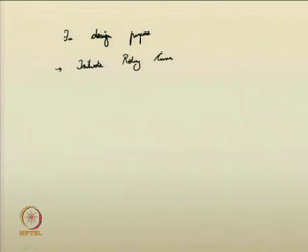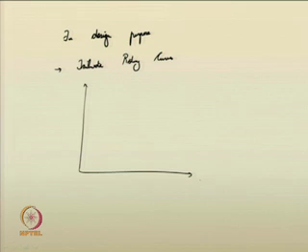What are these tailwater rating curves? For the given location, wherever the stilling basin is designed, wherever the tailwater will be coming after that in the downstream of the source of the jump, you can determine for various discharges the corresponding tailwater depth.